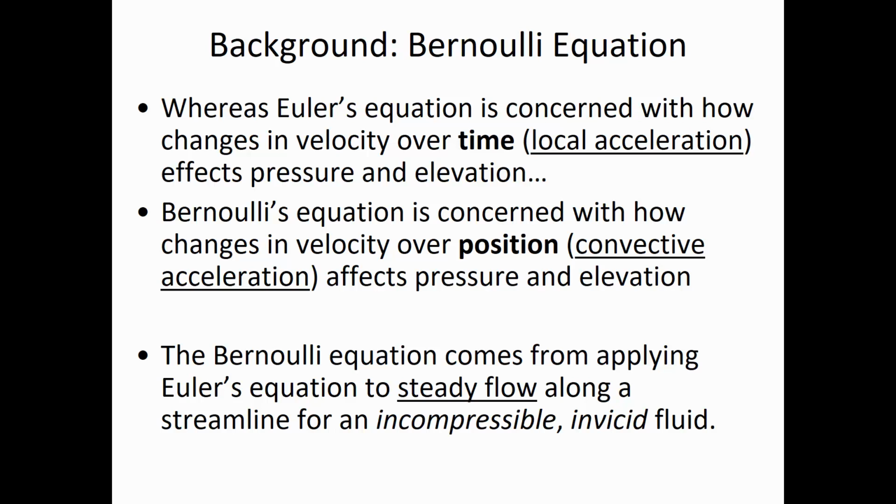So we have some sort of a fitting, like maybe a nozzle, where there's something that's causing a change in velocity with respect to position. In this narrow diameter section, the velocity is going pretty fast because it's a small diameter pipe, and we've got this much larger cross-sectional area where the velocity is slower, and so I made the arrow a little bit shorter. So what we're saying is that Bernoulli's equation has to be steady, so the flow conditions aren't changing over time, they're just changing as a function of position.